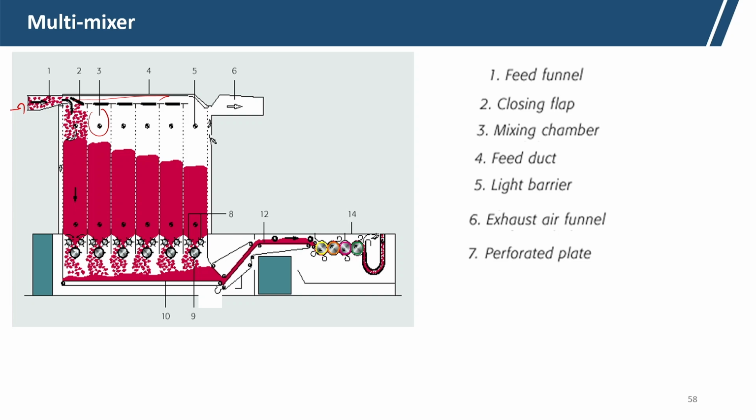The perforated plate is there, and then 8 is the delivery roller at that point. So, these are the perforated plate and delivery roller, and then the opening roller; here is the opening roller, okay. 9 is the opening roller and blending conveyor. So, the fibers are coming vertically and then through the conveyor they travel towards the delivery point, okay.